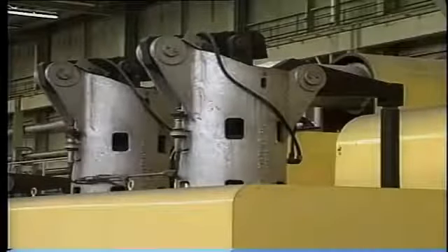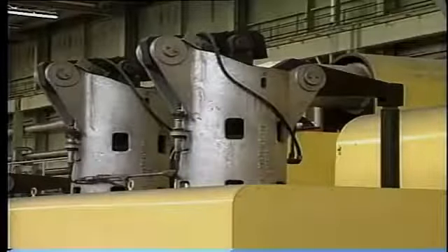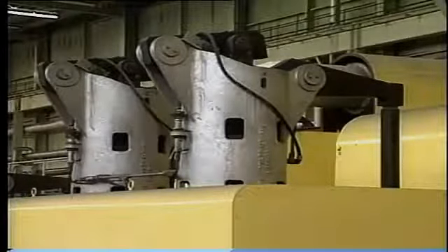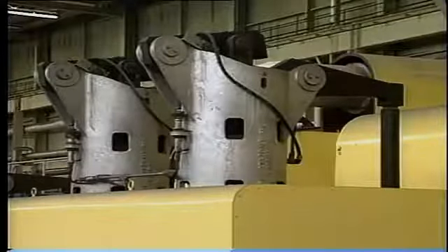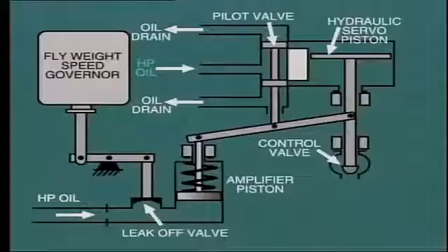On large turbines with multiple control valves, a considerable amount of power is required from the power cylinder. In this case, it's usual to employ a double relay type of pilot valve. In this arrangement, we have high-pressure oil above and below the piston.